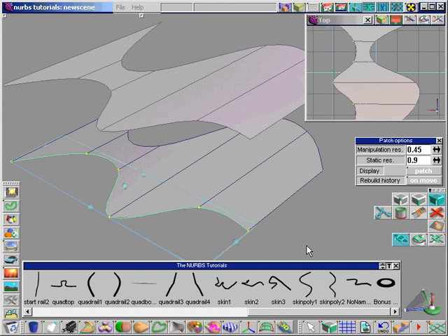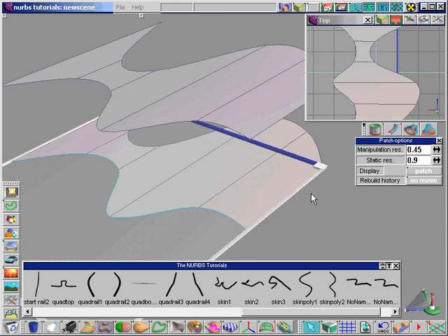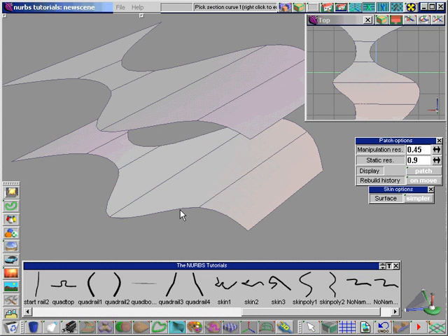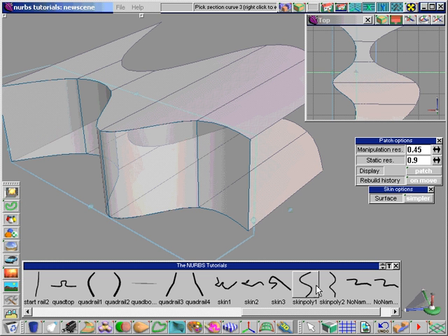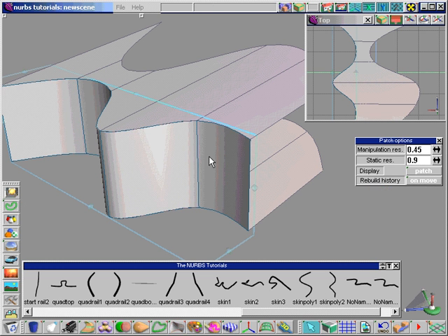Unlike using the Blend or Stitch tool, this method creates a separate patch without construction history. Using Skin, you'll have to glue it all together when you're done. You can use a combination of the Blend and Convert to Plain Patch tool to accomplish the same result.